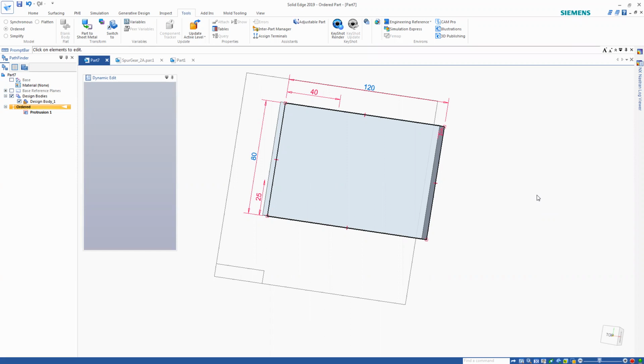If you can remember these things, then of course you can do that. But imagine with a large number of components, you may not be able to do that. Or else you might sometimes update a wrong gear wheel. There are almost similar gear wheels, there are many. So the best thing is to relate them with formulas. So then when you update, you don't actually have to worry about that. For that to happen, you have to be careful, because when you do it the first time, do it correctly and test whether it's going to function or not.